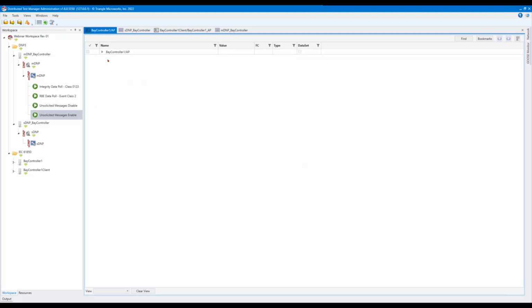So, as Christoph mentioned, 61850 is kind of 3 communication protocols rolled into one, as well as a whole engineering process, which will be the topic of our next webinar. And at the center of these 3 different communication protocols and engineering process is the data model, which is what we see here. Right now, it's just 1 row, and that's because the 61850 data model is hierarchical. It's one of the signature features of the protocol.